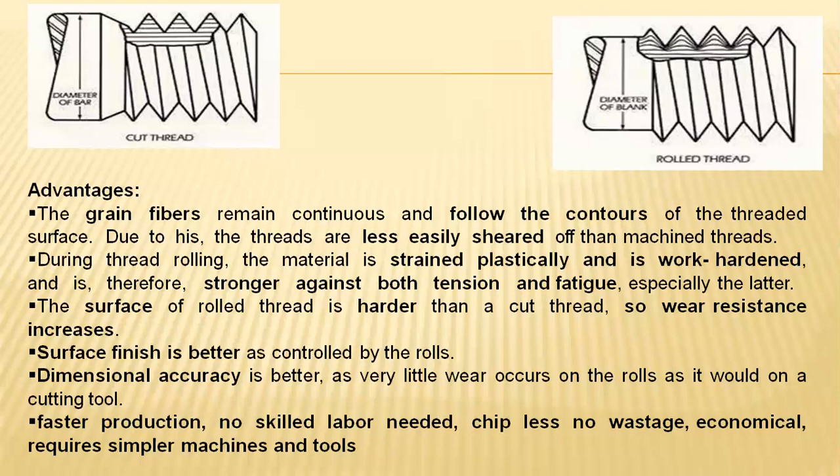Particularly during this thread rolling, the material is strained plastically, and even it is work hardened, which leads to being very strong against both tension and fatigue.